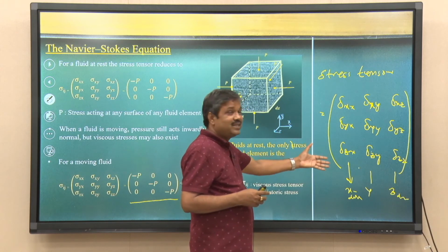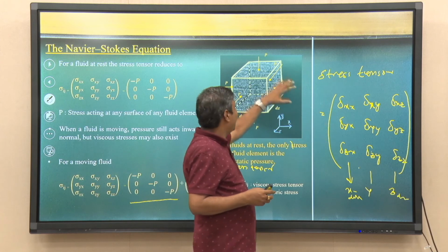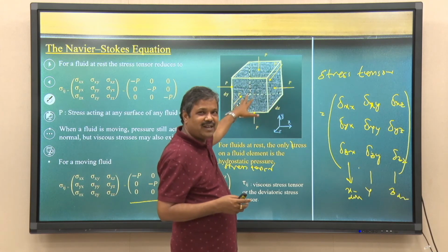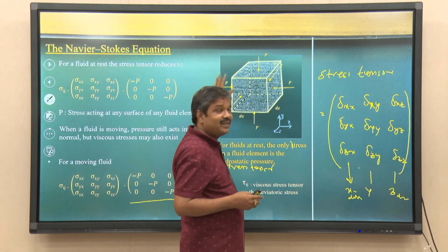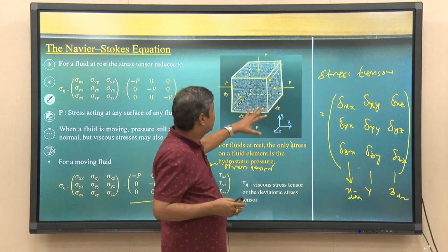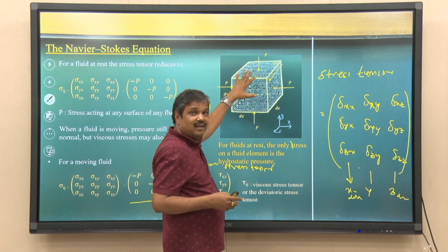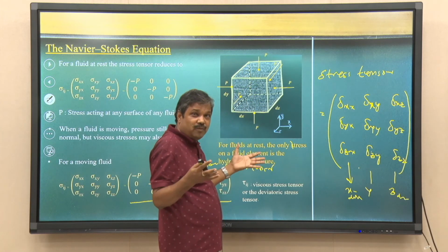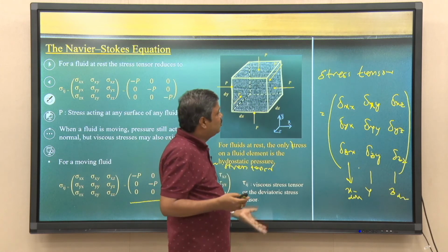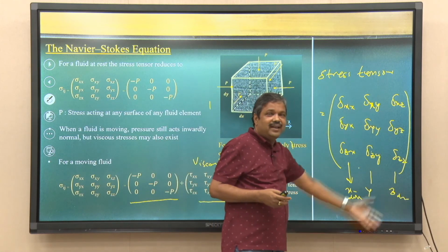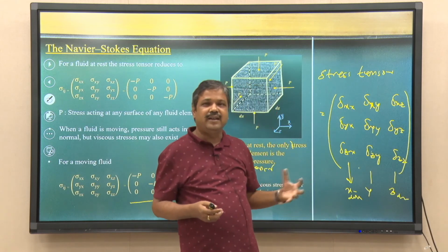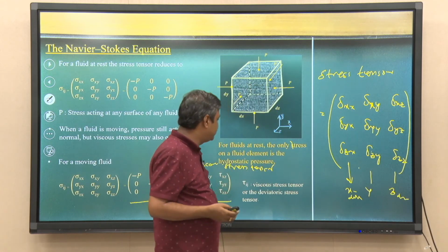what it is. Always think that this is a stress acting on this surface. That is what you have to visualize. These are the stress components acting over the surface, a parallelepiped, or, in a very simple way, you can understand it as a cube. Over that cube surface, I have an internal resistance force per unit area. And here the viscous components play the role.